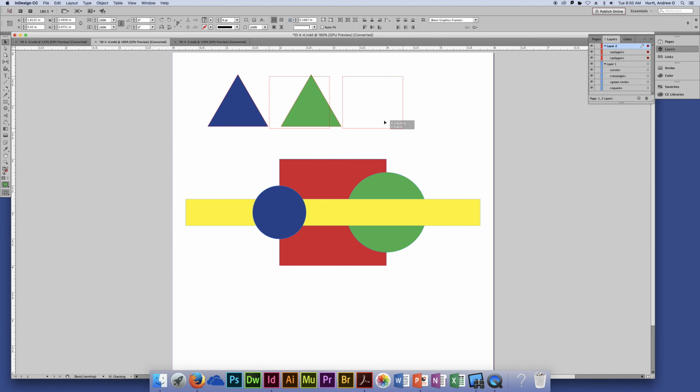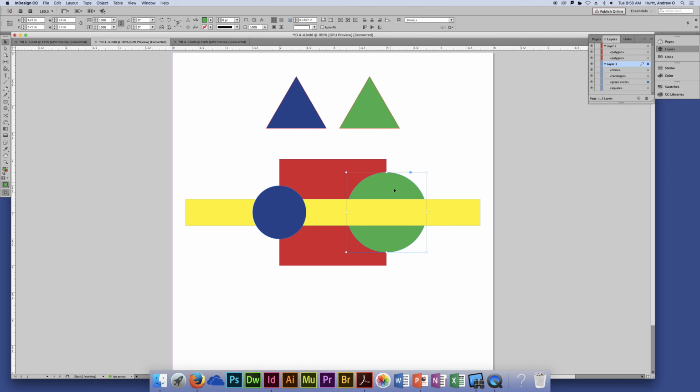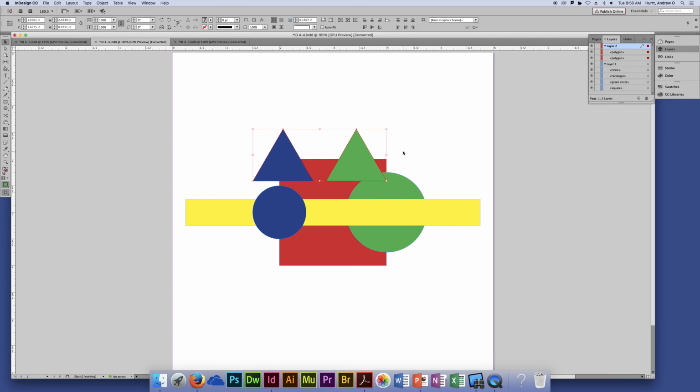And you'll see already there's an indicator with the layer. When you select the object, you have a red guide, I guess, or the resize handles and everything are red, versus when you're selecting this one they are blue, to indicate a visual indication that those are on two different layers. So since this is on a different layer that's above all of these, no matter what, they're going to be above